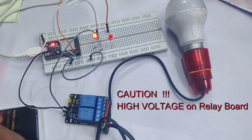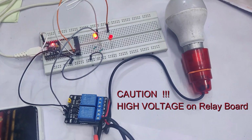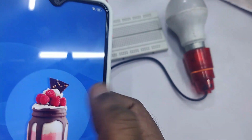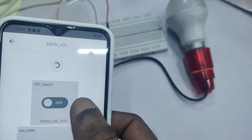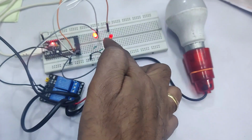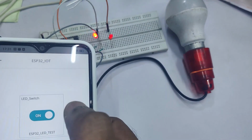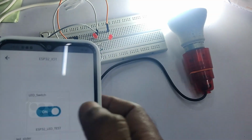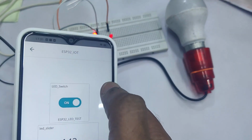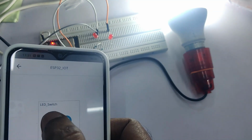Now let us check it. Provide the AC supply and be very cautious. High voltage will be on the relay board. Open the mobile app. Now you can see the LED is on as you have initially provided high. Now touch on the LED switch. The device is on, and again touch on, device is off. So the app is working perfectly.